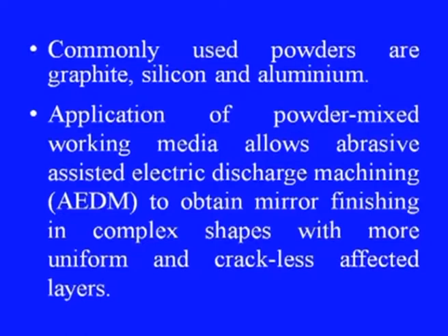Commonly used powders in this process are graphite, silicon and aluminum. Application of powder mixed working media allows abrasive assisted electric discharge machining, AEDM, to obtain mirror finishing in complex shapes with more uniform and crackless affected layers.